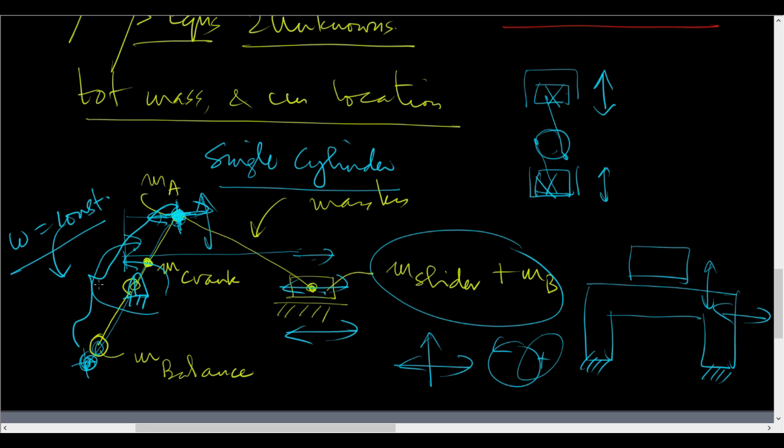And then what happens is, you see, if I have one mass that goes like this and another mass that goes like this, then the vertical accelerations of these two will be cancelled, and all that will be there is a horizontal unbalanced force, and that horizontal unbalanced force can be chosen to balance this one. But what such a thing does is, you can't obviously put the rotors exactly in the same place. They're a bit nearby by the same arguments as we were saying earlier.